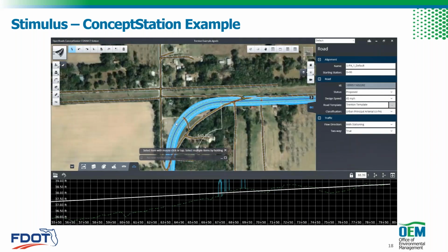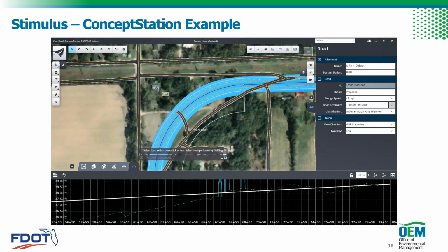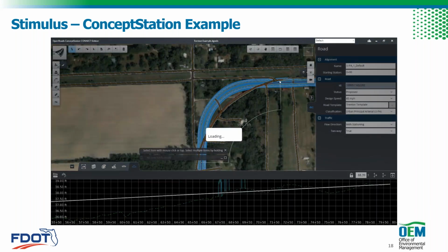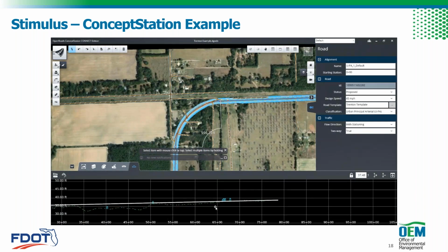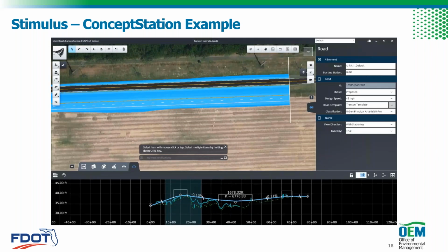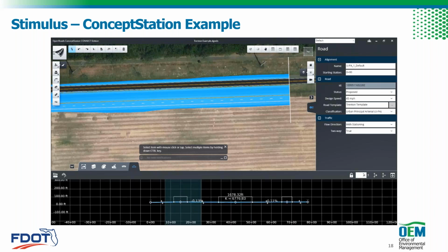And now we can come in and adjust the horizontal curve information, you know, to suit our needs there. You could either type it in or you can adjust it manually. And you can see here we have a profile, right? So it's like, voila, we went from a simple profile there that was in there by default to something that actually includes K-value information. This information can be exported and utilized as well, okay, downstream. There's your XML files again.